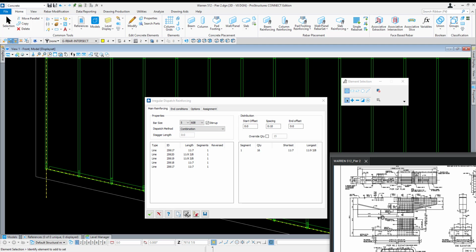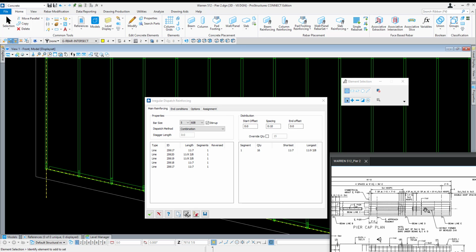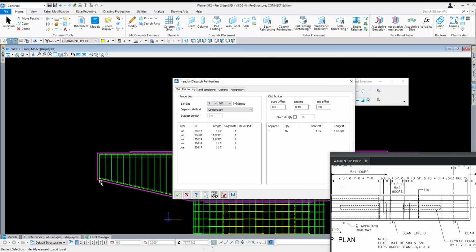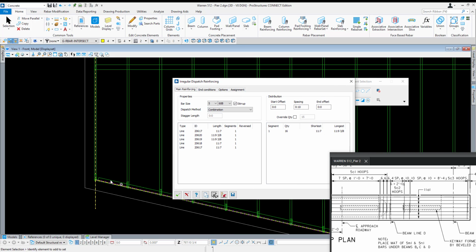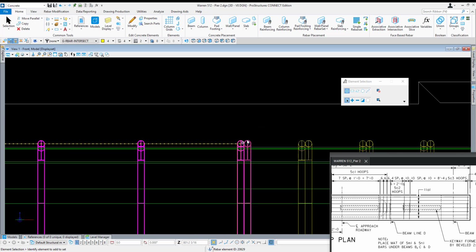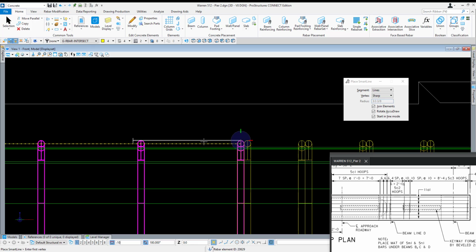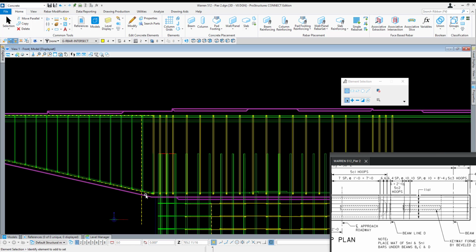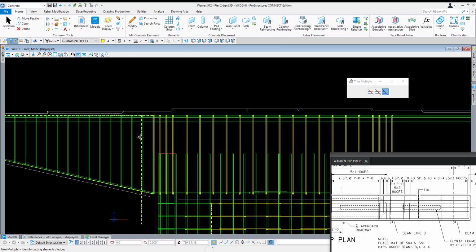let me check and make sure my spacing is good. We are at, I believe it said 10 inches, 10 inches. Good, okay. And I'm just going to go ahead and check mark this for now. I know this set that I modeled actually started right there. So what I need to do now is come over 10 inches and place my line. And now I'm going to trim multiple, both of my guidelines there, to this line.